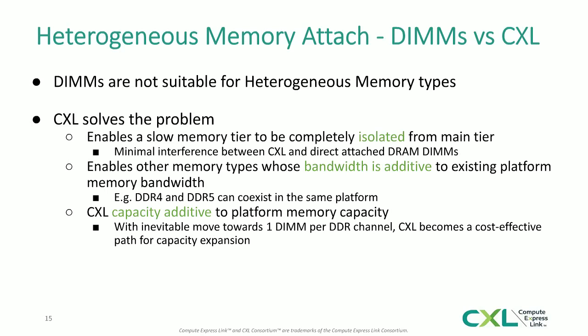So Prakash talked a little bit about some of the challenges with attaching different memory types in the same fashion on a DDR bus, for example. So ultimately, DIMMs themselves are not necessarily the ideal form factor for all of these combinations. And the way CXL helps us address some of this is that now we have the opportunity basically to isolate different tiers of memory from each other. So we don't have to share a bus anymore, and we can put